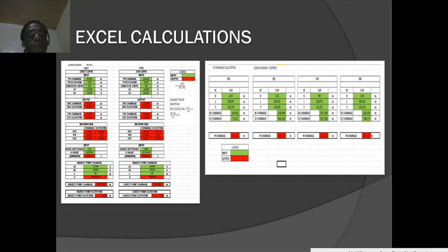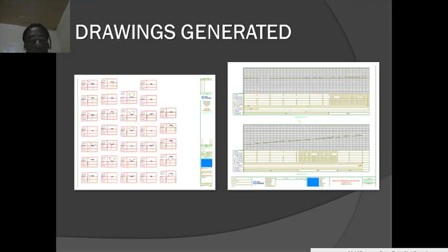As well as that, Civil Designer also outputs the highest and lowest point depending on if it's sag or a crest, and that is why I included it in the spreadsheet. If you can see at the bottom, there's an X value, which is used to find the lowest and highest point. So if you punch in the information needed by the input, it will also give you the highest and lowest value. The same goes for the horizontal. Using just the green as the input, which Civil Designer also generates, and then the output is what is calculated for you.